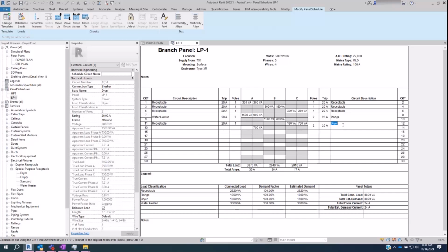All right. So no, we don't put 10 amp breakers in panel boards. That's the easiest way to say that. We don't use 10 amp breakers because that's not an AC thing. And most of the time, 20 amp is acceptable when it comes to stuff like this.